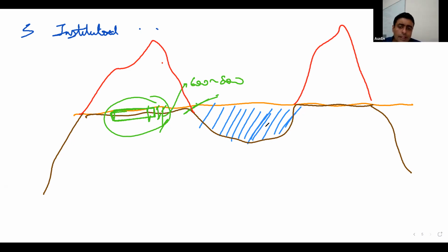So generally in road projects, you will see that you try to manage cutting almost equal to filling for optimization, isn't it? But this was actually an institutional building where a lot of things were interconnected. So your service lines were interconnected, your water supply schemes were interconnected with each other.